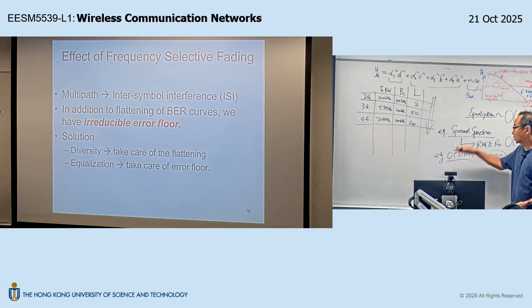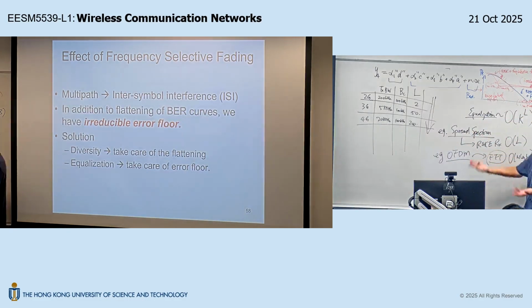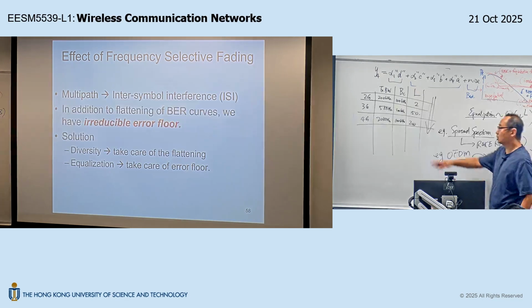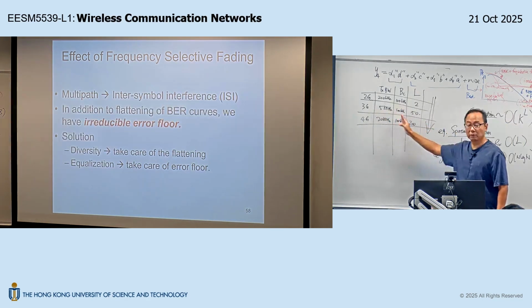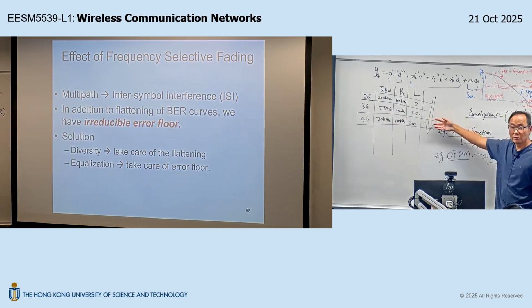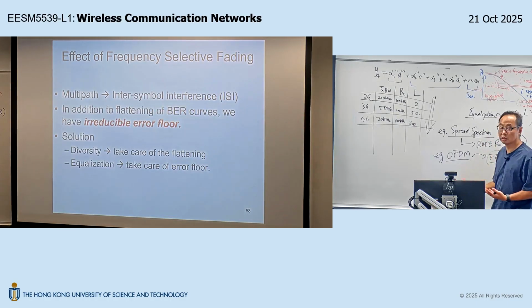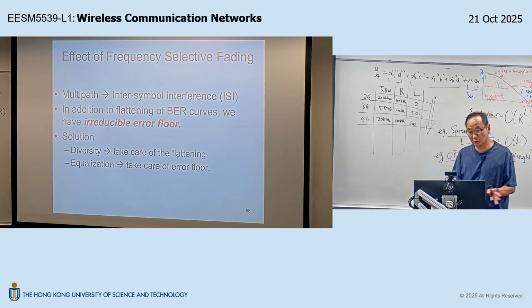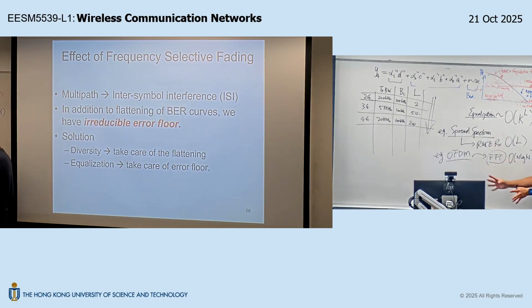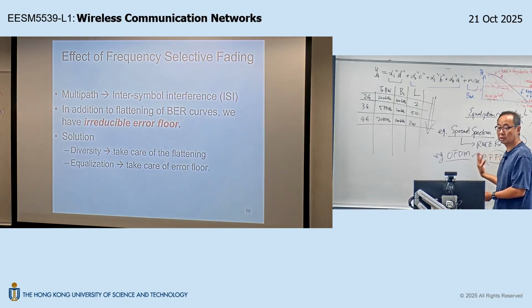So these are two examples of why it works, why it enables such wideband transmission over an outdoor propagation environment, and you can still overcome this irreducible error floor. The reason is that the signal transmitted by the transmitter has various built-in structure, and that provides opportunities for the receiver to exploit the structure to achieve low complexity equalization.